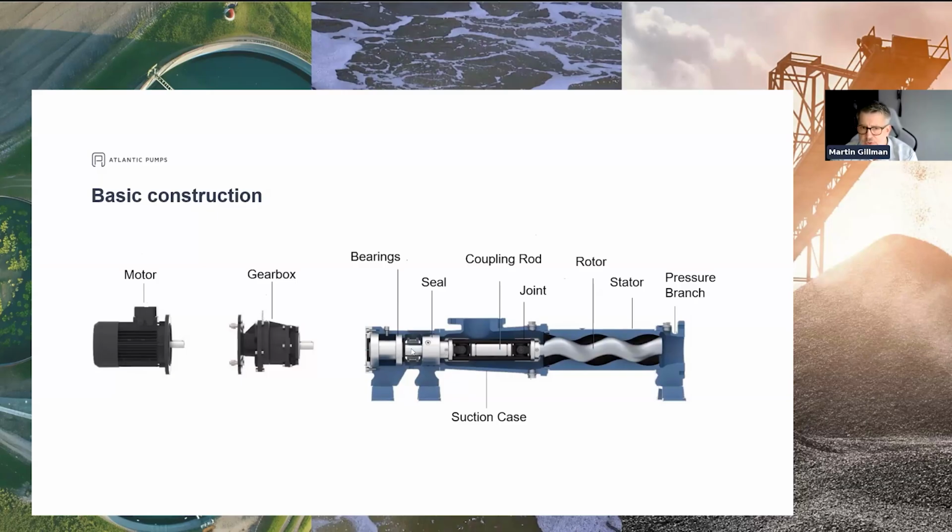Okay, most modern variants will have what we call close coupled, so it will do away with that set of bearings, and the gearbox will couple directly to the rear, just to the east here, or to the right hand side of that inner bearing. It will directly couple into the input shaft, and it will rely solely on the small bearing at the front of the gearbox here to stabilize the machine. It's okay for lighter duties, for general service, sludge transfer and things like that, slurry transfer.